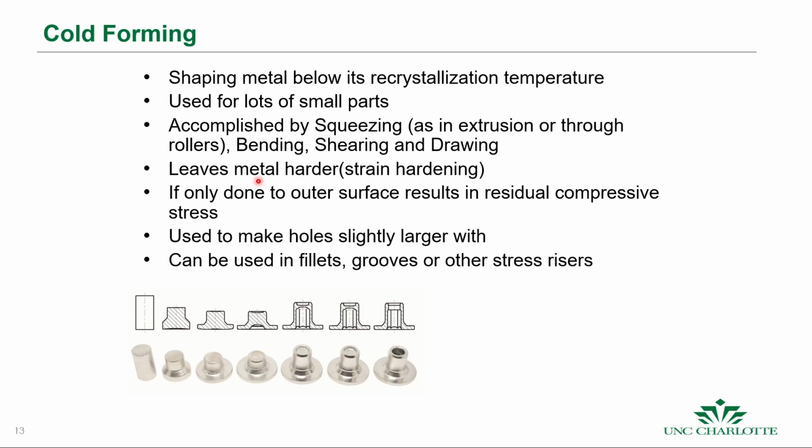Okay, so if we do that just to the outer surface, then it results in a net compressive residual stress. Sometimes this is used if you have holes. They'll undersize them and then come in and cold form them to make them slightly larger. By doing that, they increase the fatigue strength of the holes. So you'll see it in fillets, grooves, and other stress risers. And this is just an example of a sequential cold work sample into a final shape.